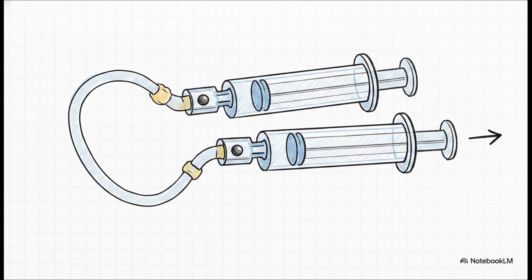And you know, you can take this whole concept even smaller. You can apply these exact same positive displacement principles to medical plastic, creating a highly functional manual pump for mere pennies. By taking a 5ml syringe, placing a miniature steel ball inside, and capping it with a cut piece of a smaller 2.5ml syringe, you create a perfect gravity-seated poppet valve. Connect 2 of these together with some tubing and a dab of hot glue, and you have literally built a working air compressor out of desk drawer supplies.